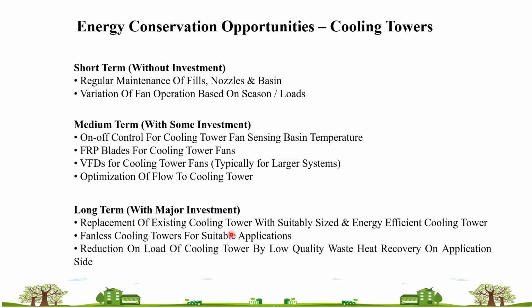Then reduction of cooling tower load by low quality waste heat recovery on the application side. We have seen the waste heat recovery in the compressor. If waste heat recovery of the compressor is done locally, then there will be no load on the cooling tower. So that's how your cooling tower load is reduced.